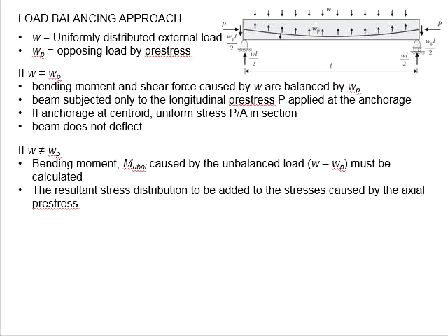The meaning of load balancing is that we can manipulate the response of the structure under the prestressing load in order to counteract the external load acting on the member, to keep the stress in the entire member within the allowable limits of the stress. Taking this as an example, the simply supported beam is subjected to a UDL external load. To counteract the effects caused by the UDL load, a curved tendon profile is provided and the tendon is prestressed.